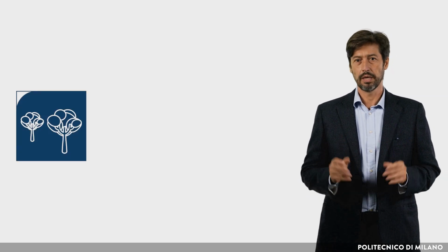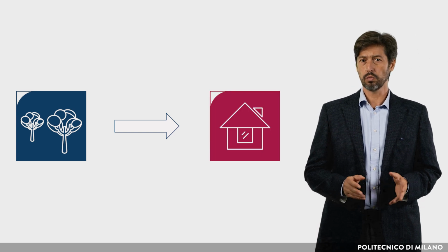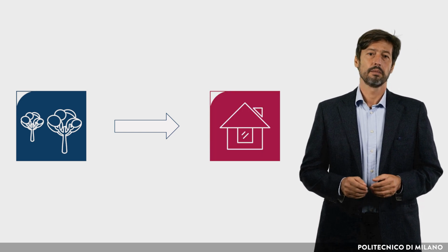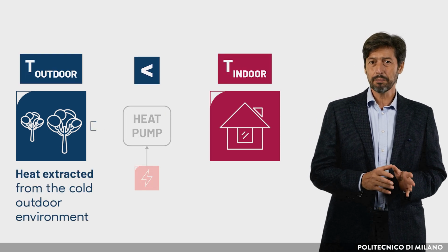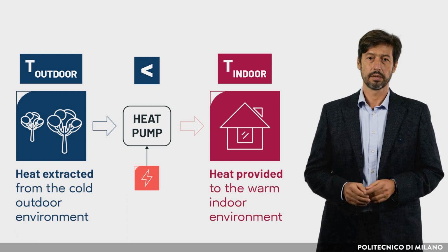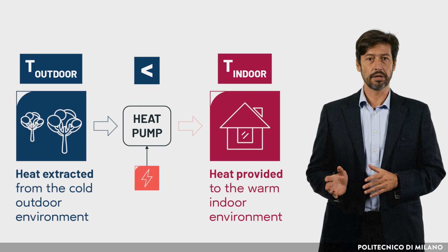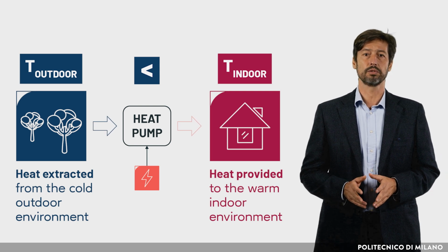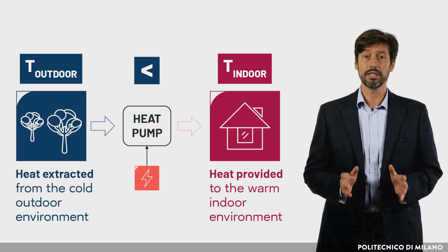A heat pump is a refrigeration machine where the cold sink is the environment and the heat recipient is the space to be heated or hot water tank. Basically, it takes the heat from the coldest system and pumps it to the warm one. No combustion occurs, so the heat is transferred with a small gap of temperatures. The smaller the gap, the higher the heat pump efficiency.